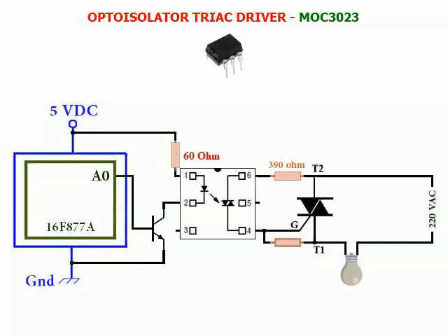First, adding a resistor between the gate and the terminal T1 of the TRIAC. This resistor reduces the sensitivity of the TRIAC gate and minimizes the effects of external noise, that may sometimes cause an unwanted electric current to flow through the gate, which ends in triggering the TRIAC at a wrong time. The recommended value for this resistor is 360 ohms.